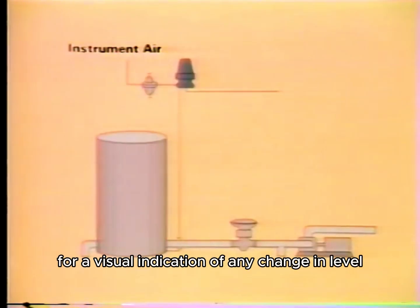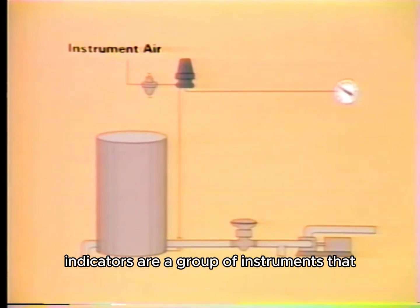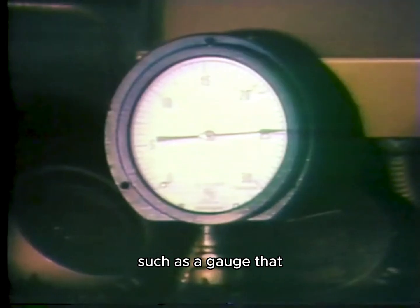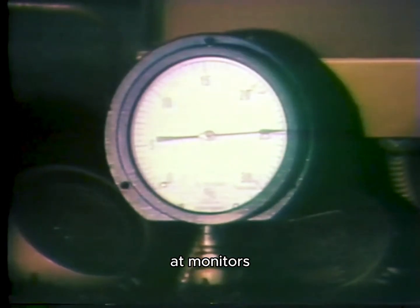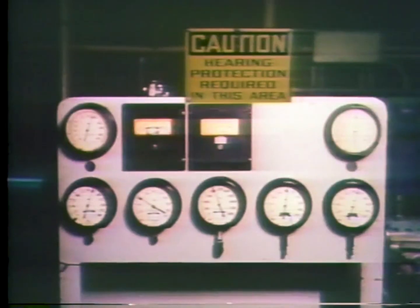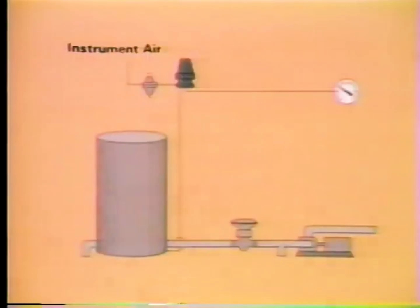For a visual indication of any change in level in our example, pneumatic systems often use indicators. Indicators are a group of instruments that use control air to operate a mechanical device, such as a gauge, that produces a visual indication of the process variable it monitors. Indicators can be located near the transmitter or at other locations. For this reason, they are commonly referred to as either local or remote indicators.